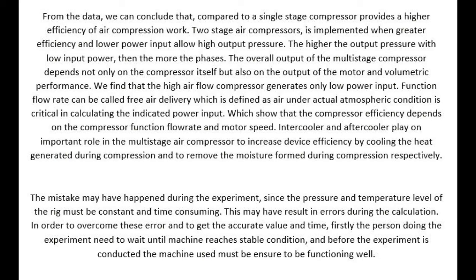The overall output of the multi-stage compressor depends not only on the compressor itself, but also on the output of the motor and volumetric performance. We find that a high airflow compressor generates only low power input. Flow rate can be called free air delivery, which is defined as air under actual atmospheric condition, and is critical in calculating the indicated power input. We show that the compressor efficiency depends on the compressor flow rate and motor speed.